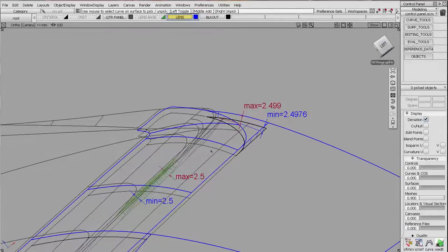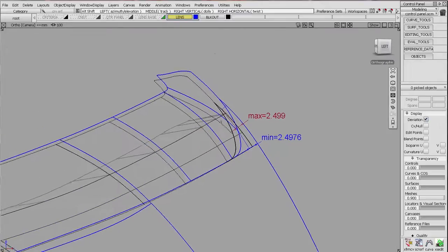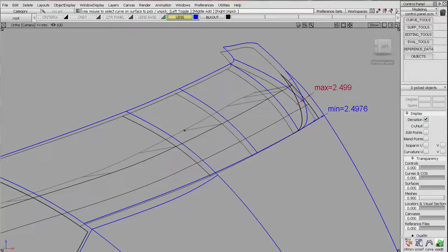And then I've also offset the quarter panel 2.5. If we turn the quarter panel off, we can now see that we have blackout offset 3.5 all the way from this lens base, 1 plus 2.5.